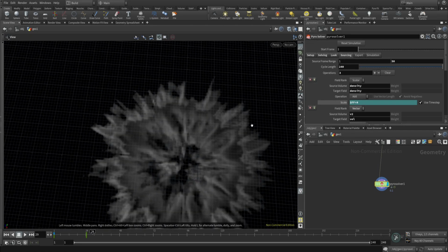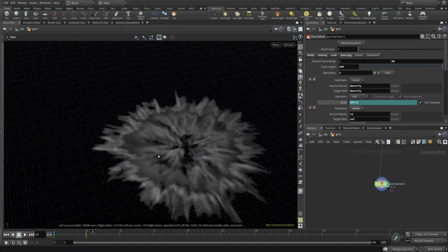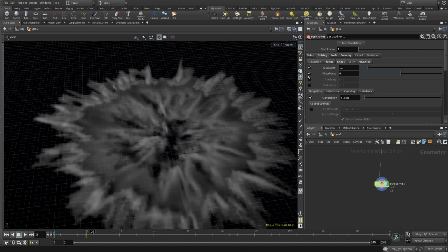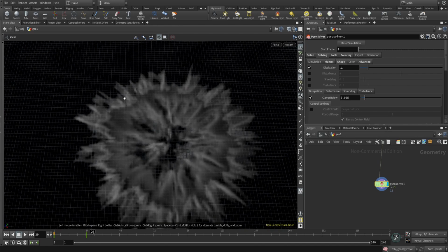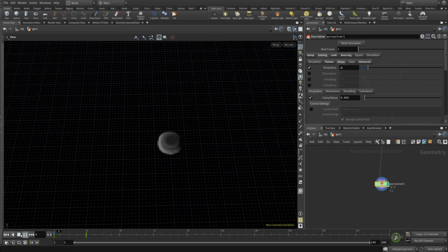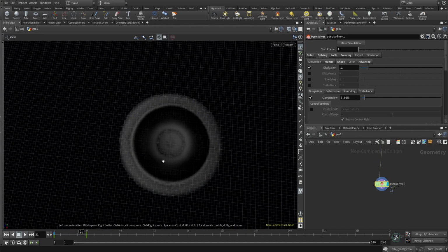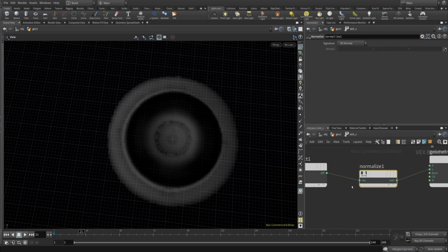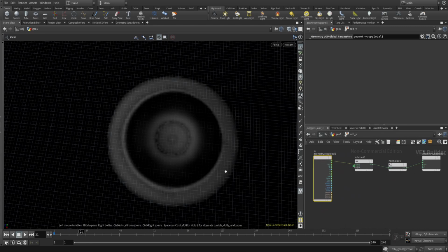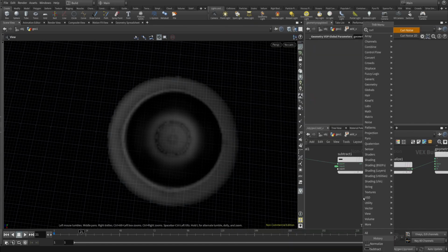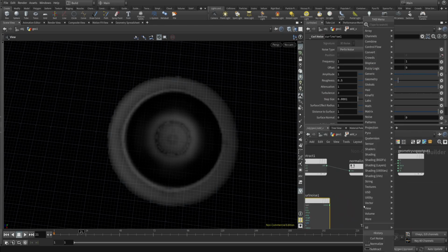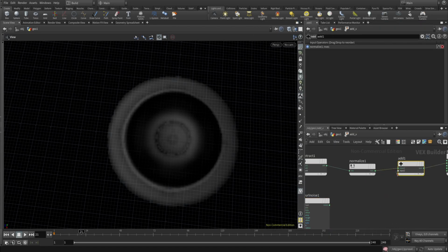Okay, now it's time to work on the overall shape of the shockwave and adding some extra details on it. For a sec, just let me turn off the disturbance. I want to see what the overall shape of my shockwave is. As you see, it's a very fine circle shape. So to fix that issue, you can just add some curl noise to your outward velocity field. I'm going to create curl noise, connect position to the P, and using the add function.